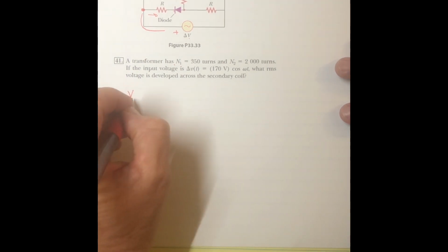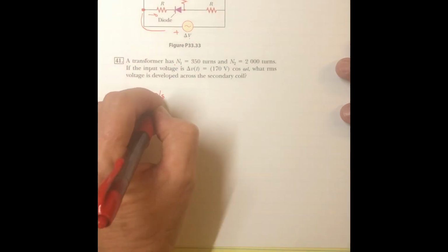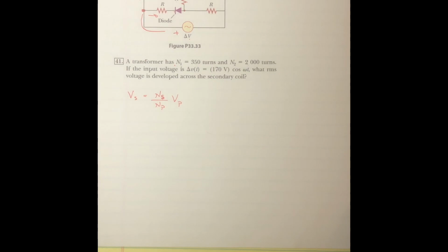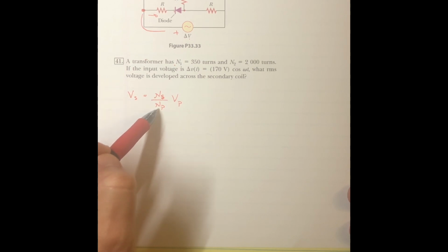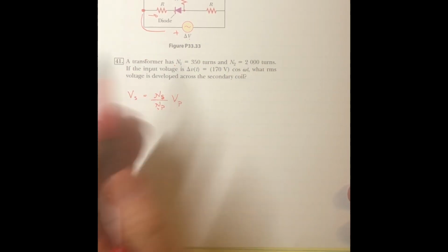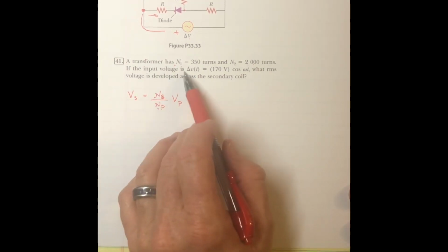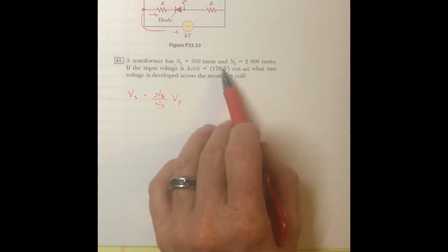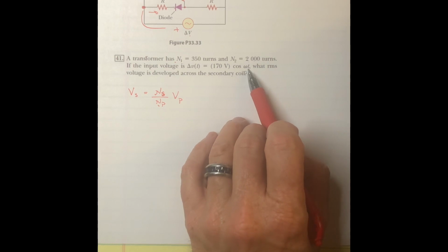Yeah, and we said this, that the voltage coming out of the secondary is equal to this ratio of the number of turns in the secondary compared to the primary, and then multiplied by the voltage originally of the primary. So if you have more turns in your secondary than your primary, which this one clearly does by quite a bit, you're going to step up the voltage to a higher level. So a transformer has, and then they put in some numbers, okay, and then this is the input voltage. So they say the voltage as a function of time. And they give us an amplitude, 170. So again, this sounds like the North America grid. They didn't give me a frequency, but if they're doing this, I'm going to say the frequency is 60.